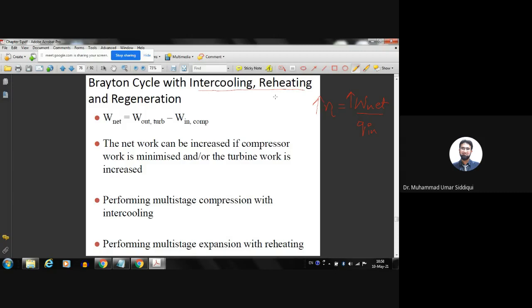However, suppose while we are compressing the gas, at the same time we cool the gas as well, then what will happen? The gas will be pressurized, but at the same time the gas is cooled, so it will not expand that quickly. So the temperature would remain in control, and as a result, a smaller amount of energy will be needed to compress the gas.